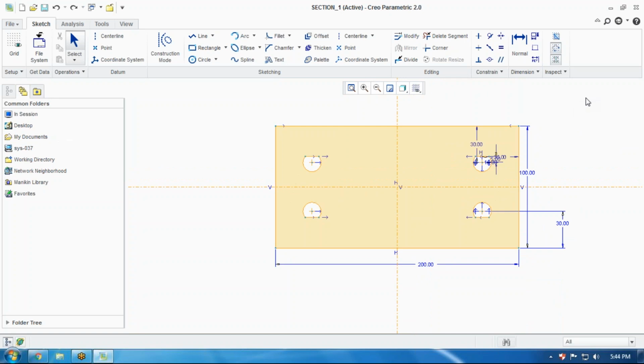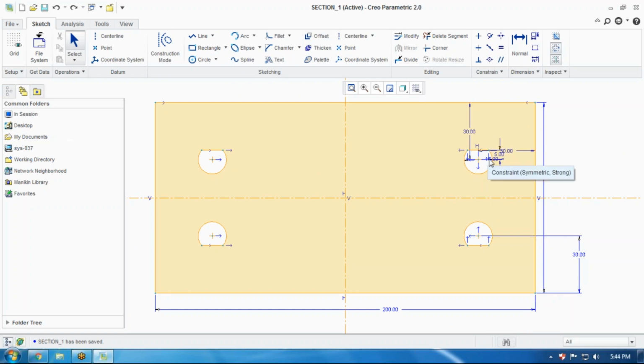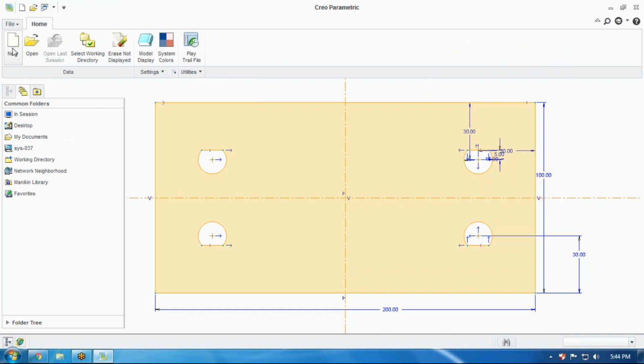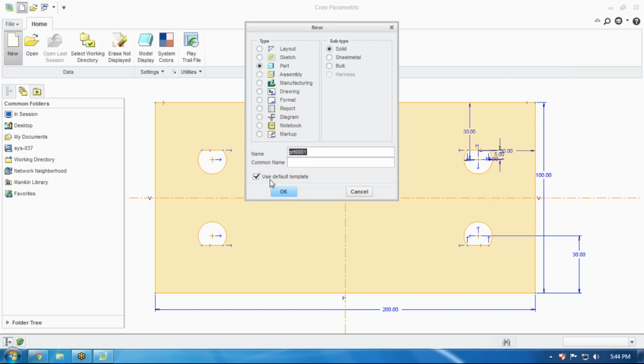So now we have to save this section. First of all, save, done, and then after that I'm just showing you preview that we can extrude this section as well. Also we can create a 3D operation, but right now we are working in Sketcher, so we cannot use 3D features. So we have to close this file first of all, and now you have to go for new file, create a part file. This thing you need not do right now, I'm just telling you this as kind of an introduction. Whatever we have done in Sketcher should be considered as a class, but this feature, which is part design feature, will be the next level, which will be done only after completion of the Sketcher workbench.